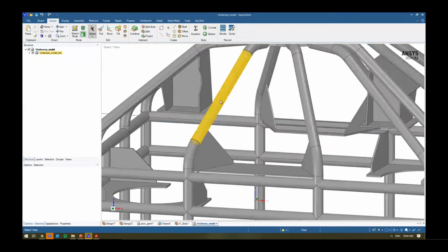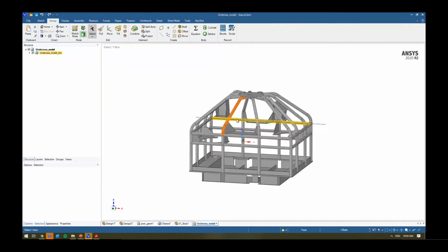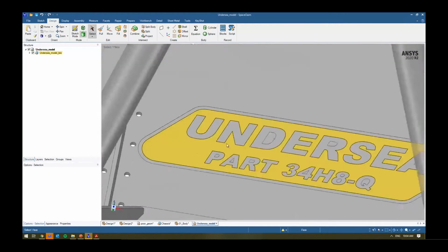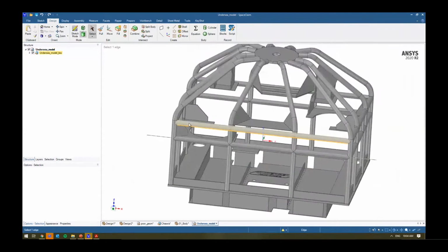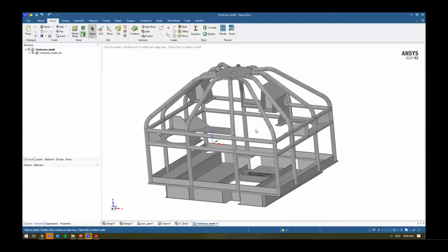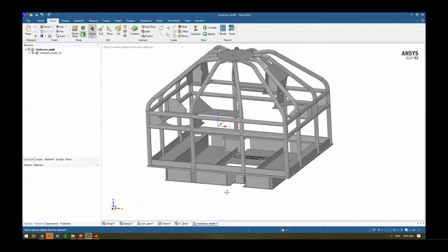Ideally, you don't want to be bringing in some of this 3D geometry, and maybe you want to make some beams out of it. There's a lot of detail around here. You probably want to get rid of that. A lot of these are just plate surfaces. There's nothing special there. So maybe you want to go through the process of mid-surfacing it as well, right? A bunch of different things that we can do in order to fix up the geometry.